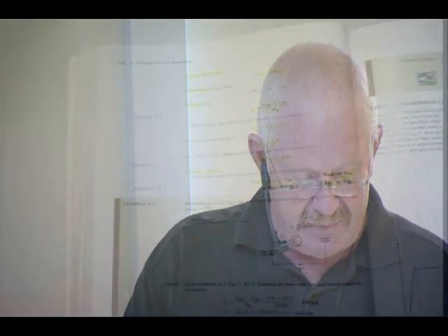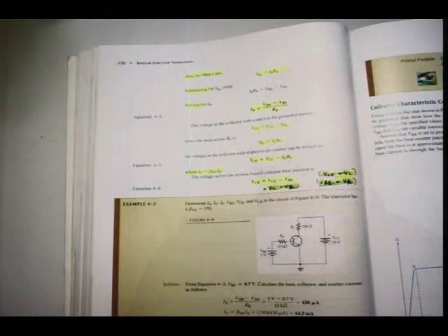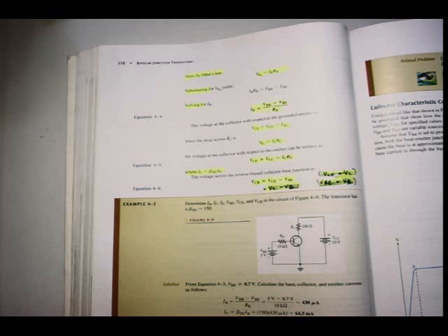And then lastly, the voltage across the reverse biased collector base junction, VCB, as we've seen, is VCE minus VBE, but we've also seen that VCE is equal to VC because of no resistor at the emitter, and VBE is also equal to VB because there's no resistor at the emitter, so it will be the same. And then, as I just mentioned, scratch it in there right next to it, so if you also want to do that, you're welcome.